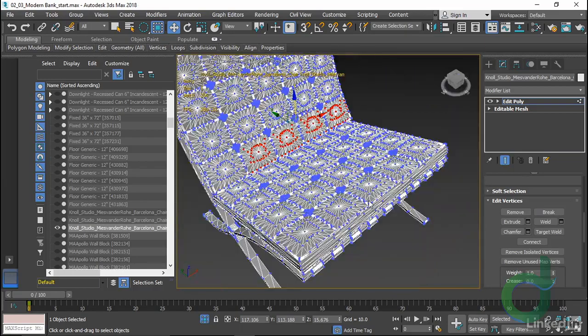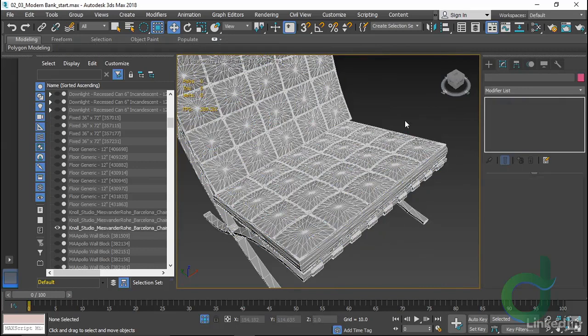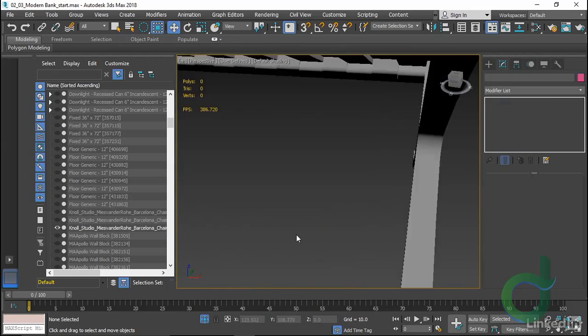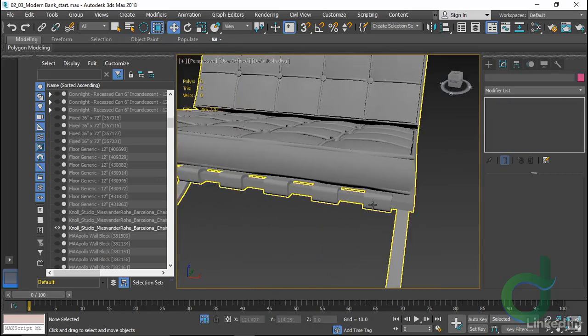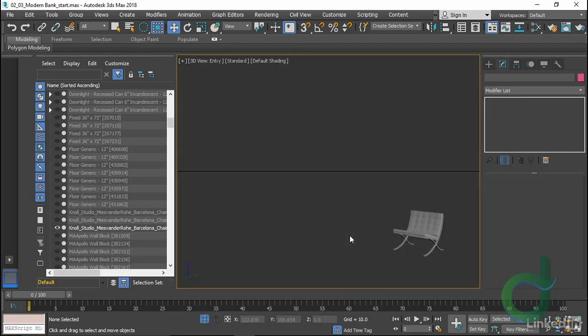There's a lot of geometry that came in, and we need to be especially cognizant of it so that this renders nicely and smoothly. What we can see here is that that one piece that I've reduced the geometry on really renders the same as all the others, and I'm in a very close view. Most of the time we're going to see an object something like this, or if we get closer, we'll be more on top of it. Even in a VR application, we're going to be looking down at it. We really have to get down and look, and it'll still smooth out nicely.